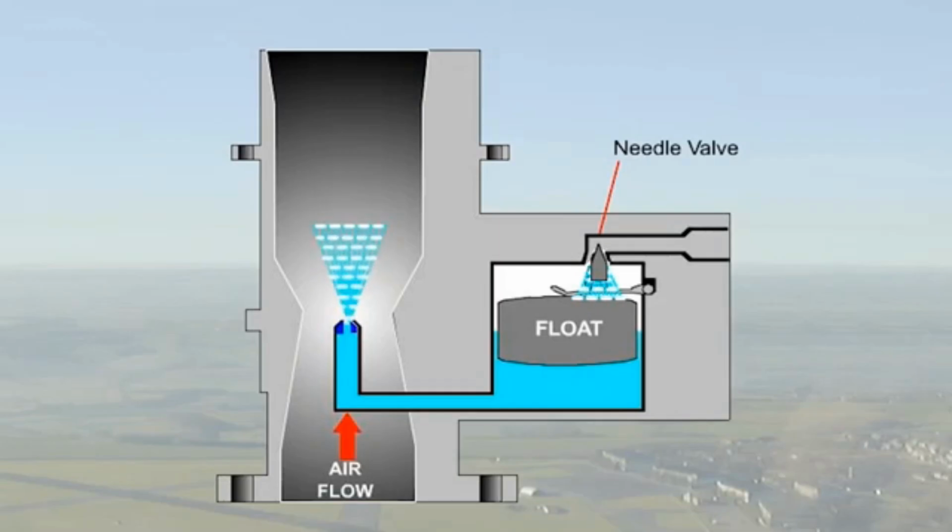In the float chamber carburetor, one leg of the U-tube is opened out to form a small tank, and a constant level is maintained by a float and valve mechanism regulating the flow of fuel from a fuel pump or pumps, delivering a supply from the main aircraft tanks.